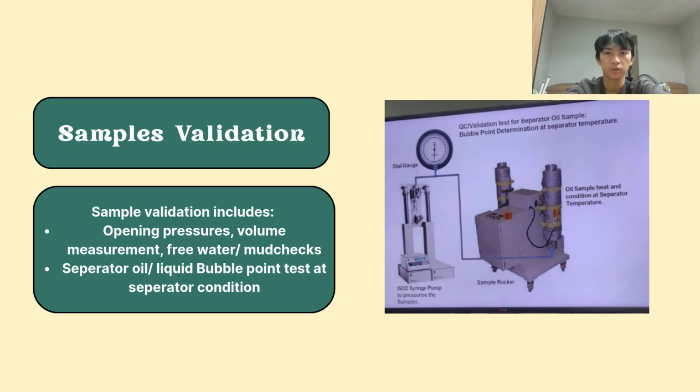So for sample validation, it includes opening pressures, volume measurement, and free water, or can be called mud checks. Separator oil or liquid bubble point tests at separator condition.